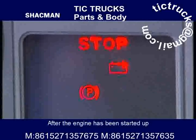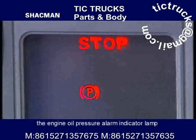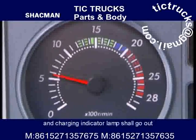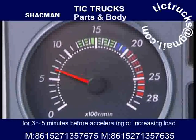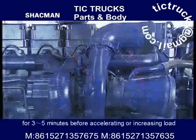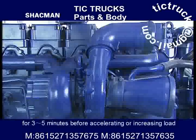After the engine has been started up, the engine oil pressure alarm indicator lamp and the charging indicator lamp shall go out. If the instruments are normal, allow the engine run at idle speed for 3 to 5 minutes before accelerating or increasing load.